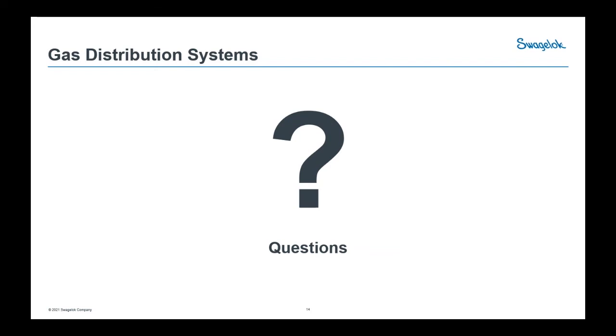Okay, great. So we have another question here that just came in. What regulator are you using in your standard gas panels here? What is its CV and uniqueness compared to other models like KPR and KCM series? So I can answer that one. For the panel itself, we select the regulator based on the application. So on those, we will use actually a KPR, maybe a KCM, maybe a KCY, depending on what the actual application is.